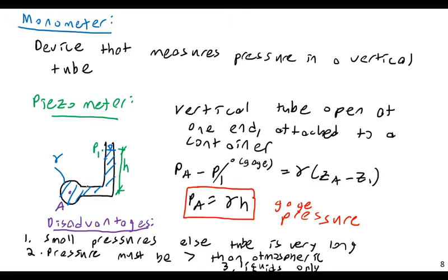And if this is, say, a boiler, and the pressure in your boiler or whatever this is drops below atmospheric pressure, well, suddenly instead of your boiler forcing water into the atmosphere, the atmosphere is going to be forcing air into your boiler, which, depending on your system, is probably not something you want. And so these things are only good for a very narrow range of pressures. The pressures need to be small enough that you don't want a 10-meter high column or something like that. So they have to be 2 atmospheres, 3 atmospheres, 4 atmospheres, something like that.